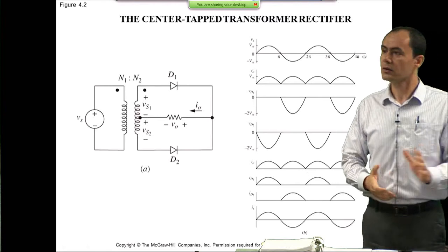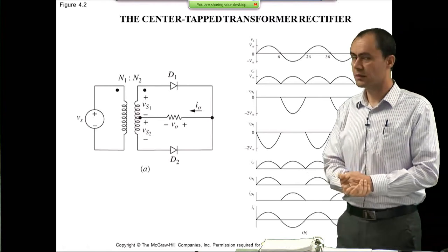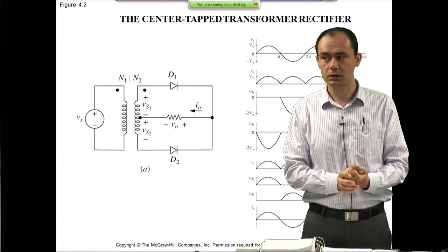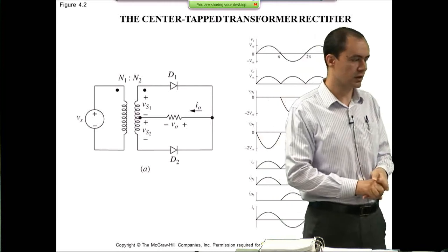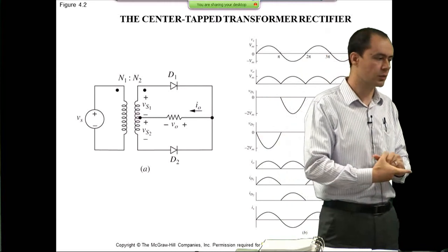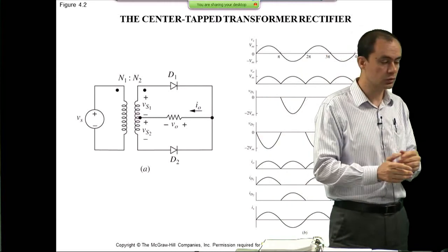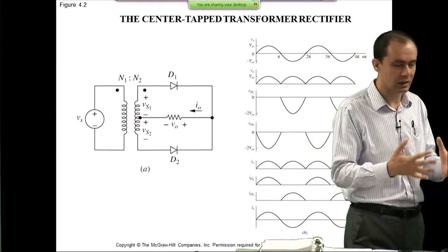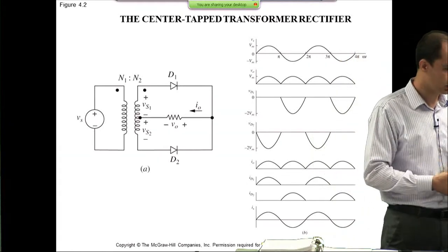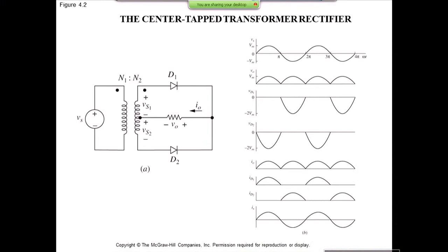Then we looked at another rectifier which almost does the same thing but with only 2 diodes, but in addition you also need to have a transformer which as well provides isolation. So it could actually be a good thing to use this if, by complying to some standards, you have to use a transformer anyway, so you can use a transformer that is center tapped on the secondary side.